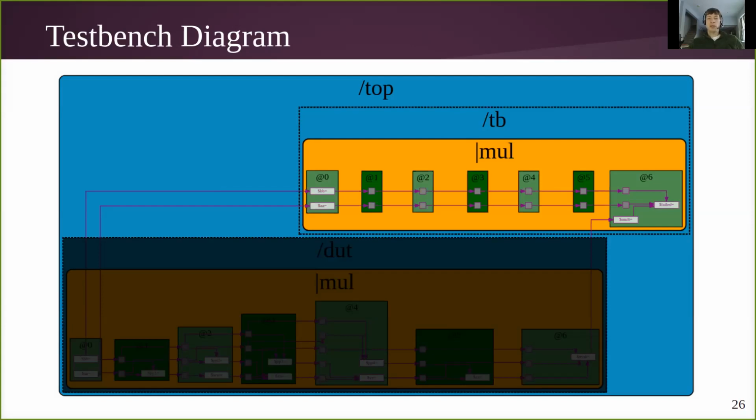So typically in verification, you'll have your DUT, which in this case is our multiply logic, and your test bench is monitoring the behavior of that DUT. It's monitoring the inputs and checking the outputs. So in this case, our check is just to do the wide multiply A and B, and make sure the output is that multiplication. Of course, here we have a 6-stage pipeline, so the inputs are early, and we have to deal with the stages. TL-Verilog, of course, is very convenient for doing that.